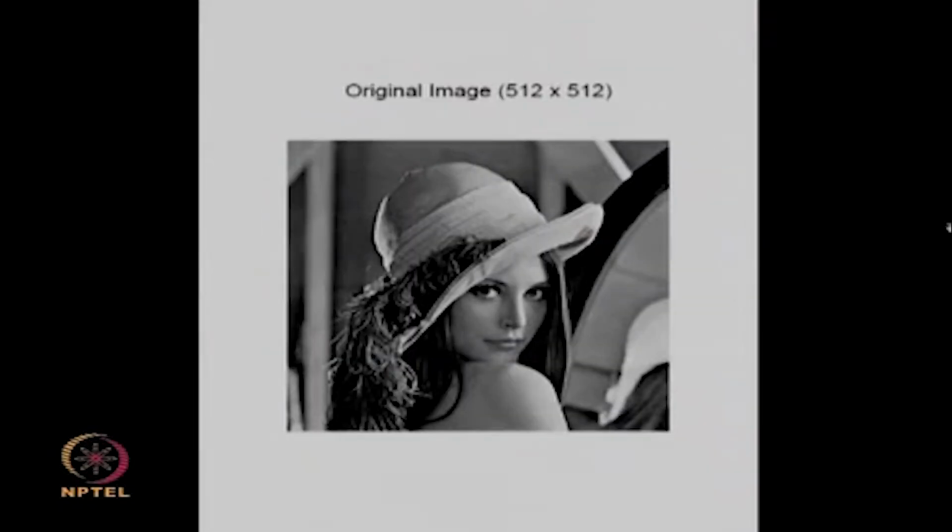So this was our original image, which is Lena, and its size is 512 cross 512. After performing the same operations as explained before, we have decomposed this original image into 4 subbands. This is my first subband, which we have called the LL subband. This is another subband called the LH subband. This subband is the HL subband. This subband is the HH subband. So it can be seen clearly from this output that the maximum energy, or the maximum information that we have captured after the first level of decomposition, is contained in the low subband.